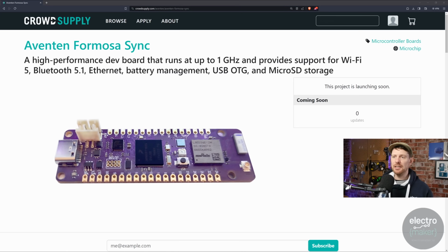The fact that you get the Wi-Fi and battery management on board is nice. A lot of boards do that, of course. Most of the Adafruit Feather line, for example, include that. But let's not forget that the controller on here, the microcontroller itself, is up there with the Teensy 4 in terms of pure processing power. If you don't overclock it, I believe the 600 MHz processor on it is the same as the Teensy 4.